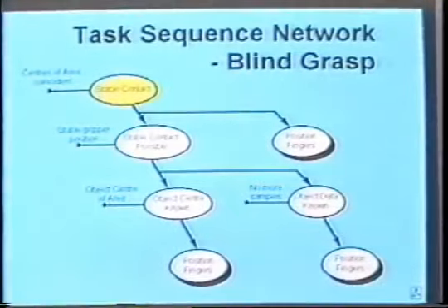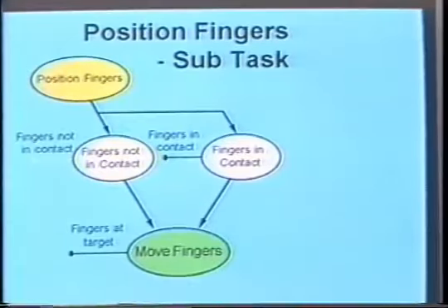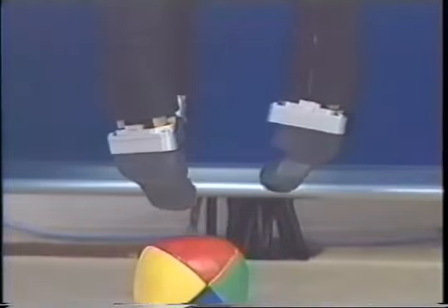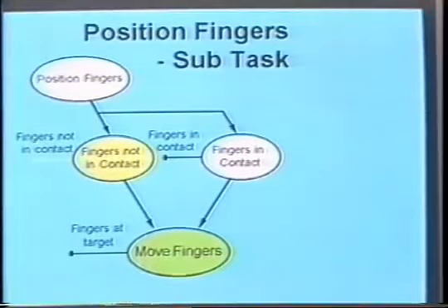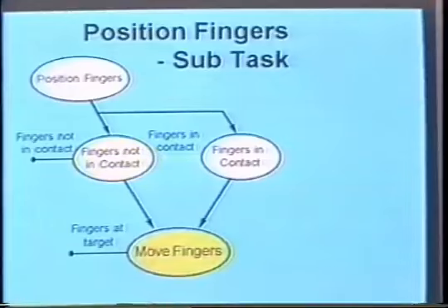For grasping and manipulation in poor visibility, we have developed a supervisory grasp planning system using blind grasping. Finger actions are sequenced to contact the object and estimate its geometry. Unsuccessful grasp attempts provide further information on object mass and friction. Geometric and semantic object descriptions are developed and used to reactively sequence grasping commands to the medium-level control. The gripper can thus grasp and manipulate without teleoperation and without vision.